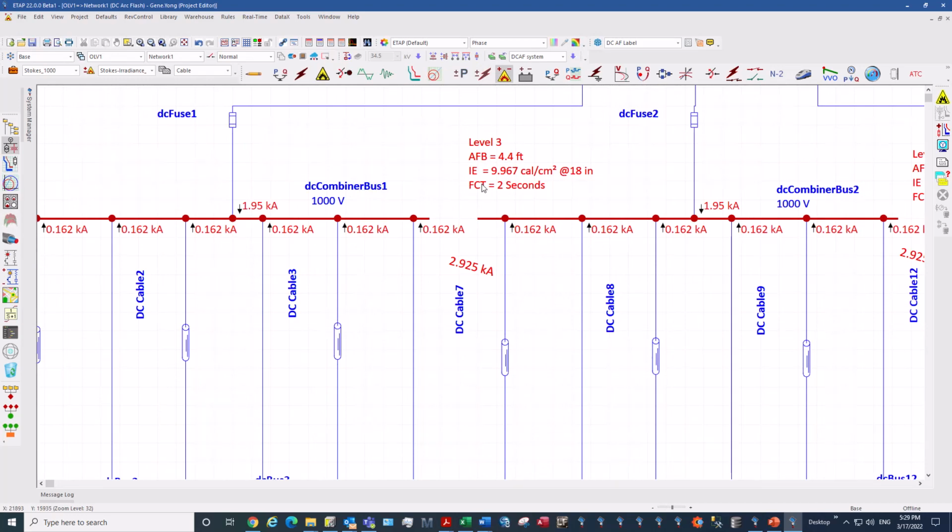So when you apply the arc elongation effect, when you're increasing the arc length, you're going to increase the incident energy. The reason being that when you increase arc length, you're actually increasing the voltage across the arc. There was an equation developed that showed a correlation between the arc length, and as it grows longer, the arc voltage will also increase. And when you have this increase in arc voltage, your arc energy will also be increased.